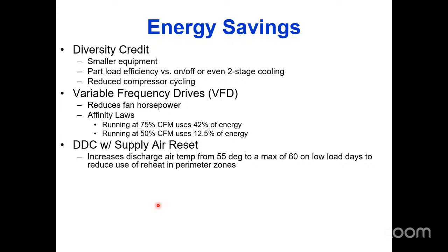That's where we set the discharge air temperature upward when it's not dehumidification season, if you will. And I set it from 55 up to a maximum of 60. You can do that based off of a surrogate outdoor air temperature, or more properly, you would do it based on communicating to the zones and comparing their indoor set point to their indoor actual temperature averages. That used to be an optional thing we did to save energy. It's now a code required thing. You have to do it by code, by energy code.